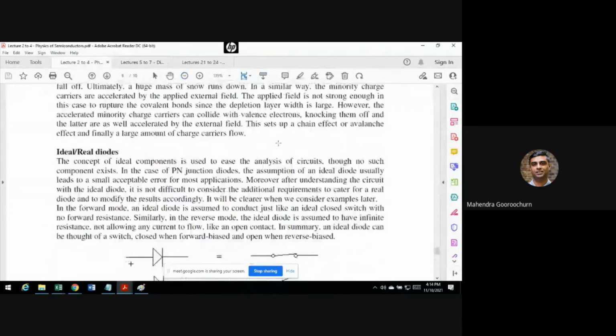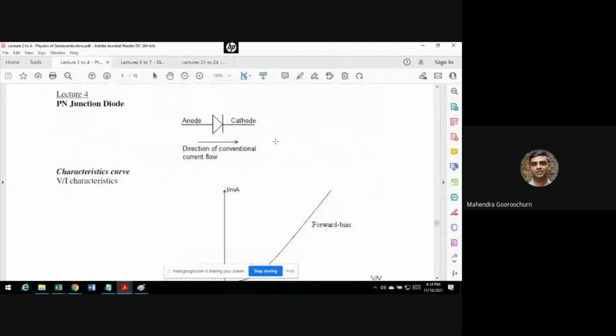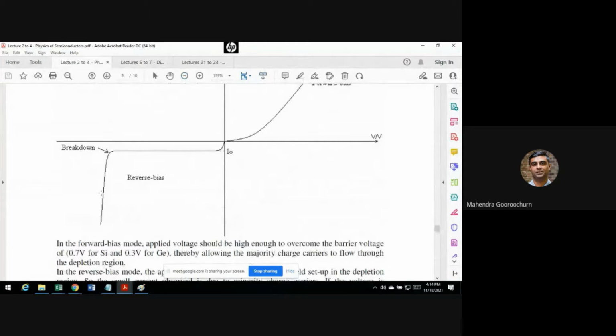This is a very important observation you have to understand well. So you're seeing that now, when I talk of 2.4 volts, I'm talking of a breakdown voltage here. So this value is at minus 2.4. This is where the voltage would more or less stay fixed. Can you see when you come in breakdown here in a Zener diode, your voltage is remaining fixed at the breakdown voltage. If it is 2.4 volts, it means the moment you exceed 2.4 volts, it would not be exceeding 2.4 volts. It's going to maintain 2.4 volts.